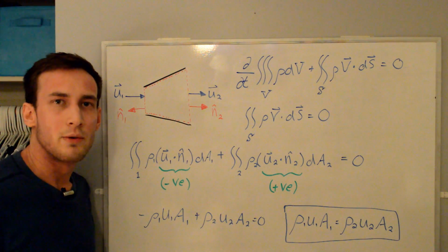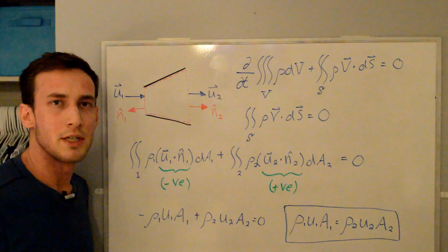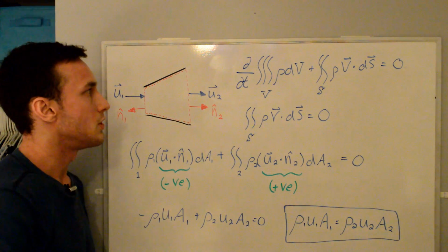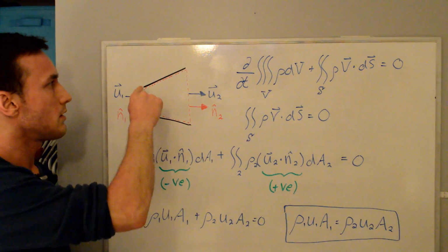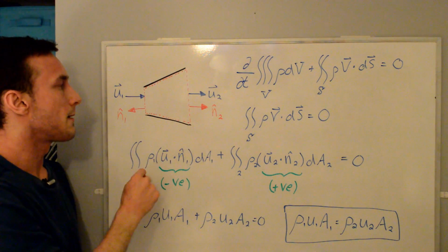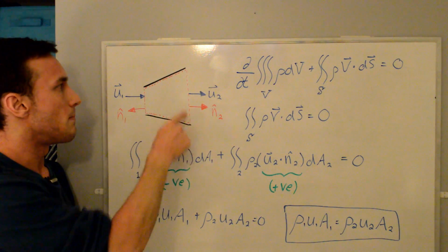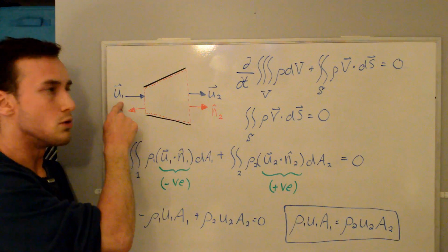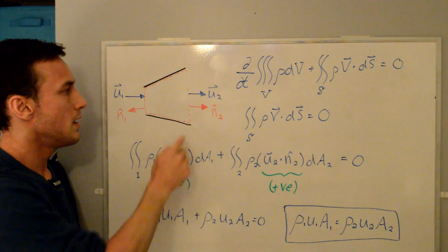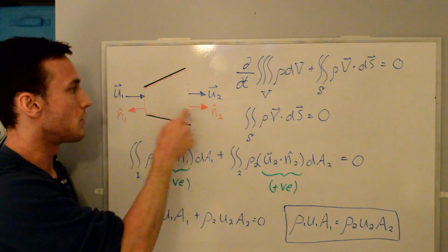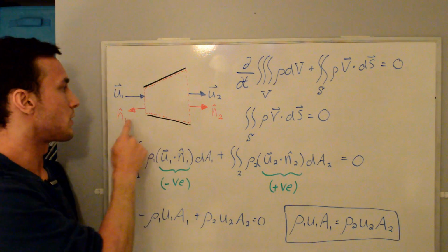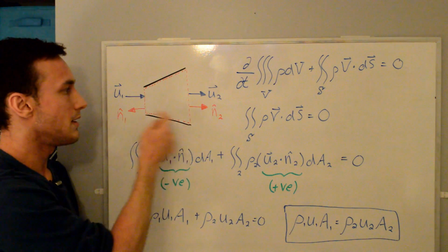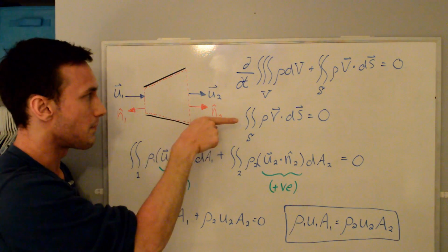So here I'm going to quickly derive the 1D conservation of mass equation. It's almost a quasi-1D because the areas are allowed to change. So I'm going to start off with the side view of the diffuser in black, and I'm drawing a control volume in these red dashed lines, so you can see the flow coming in at a velocity u1, leaving at a velocity u2, and by definition we draw the surface normals of this control volume outward on both sides. So you can see the normal n1 hat is out to the left on the inlet, and the outlet n2 hat is out that way.